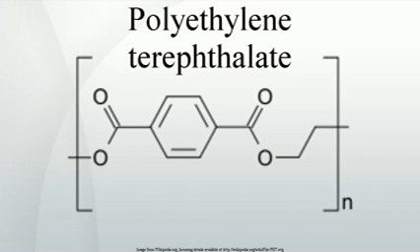The destruction of the hydroperoxide groups is, with other processes, already carried out during the last step of flake treatment, for instance by adding H3PO3. The partially glycolyzed and finely filtered recycled material is continuously fed to the esterification or pre-polycondensation reactor. The dosing quantities of the raw materials are being adjusted accordingly.